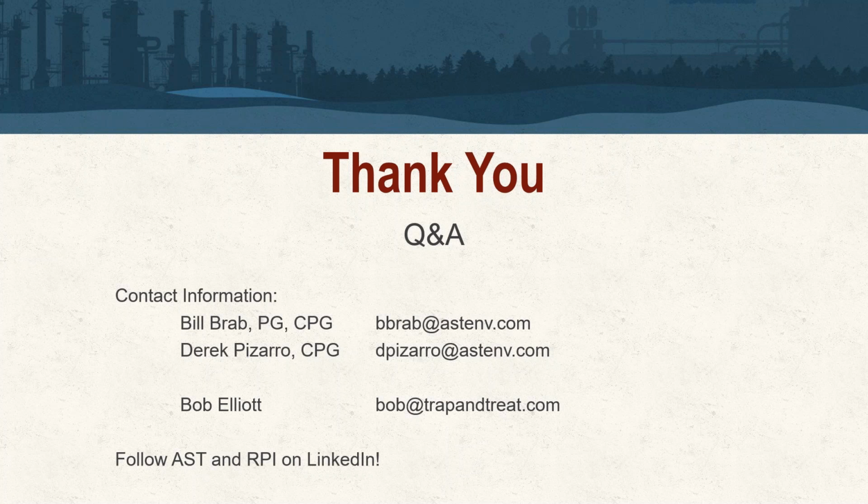So this really is a big picture, right? Fractured bedrock. We're not trying to say this is a simple solution, but we're also not trying to say it's very complex. I actually liked Bill's case study a lot because it shows that not just sustained treatment through the reagent, but by targeting its emplacement, it favors that sustainability of the treatment system in the subsurface over long periods of time. And you only get that by accurately targeting zones, getting the right loadings for those specific zones, and then knowing if in the future, again, setting expectations up front in the RDC, will we need to potentially in the future, depending on the size of the site, come back and augment this?